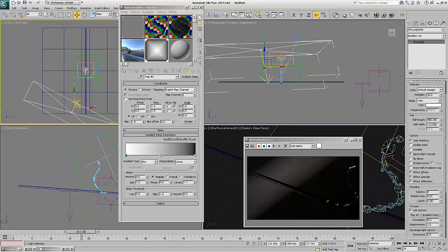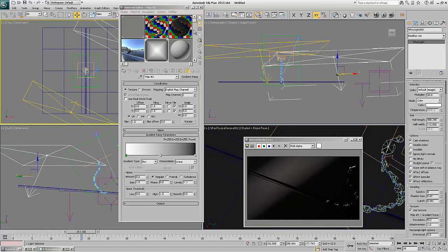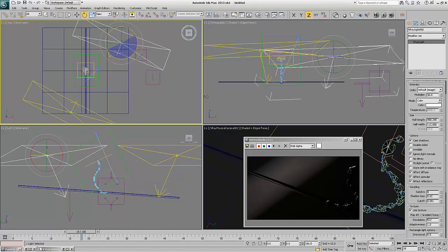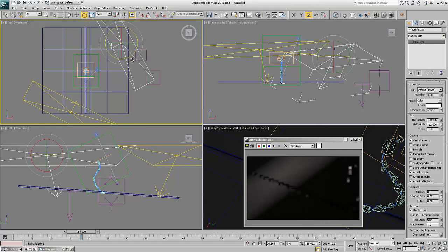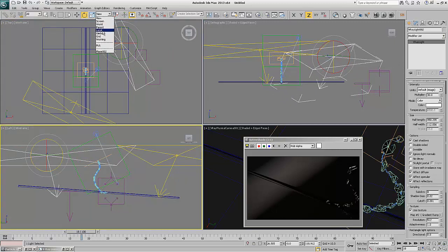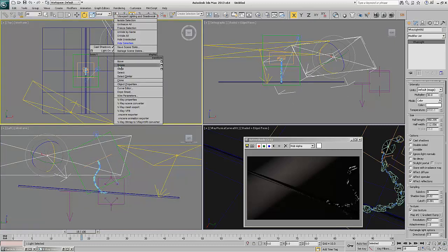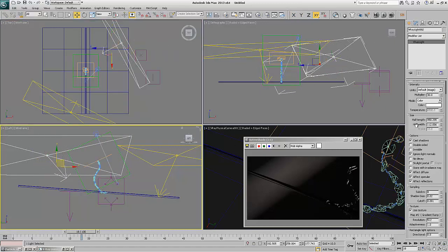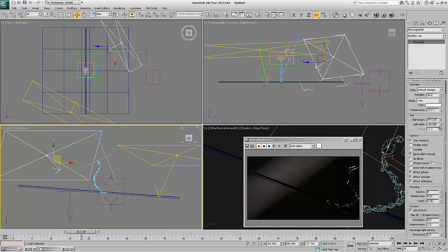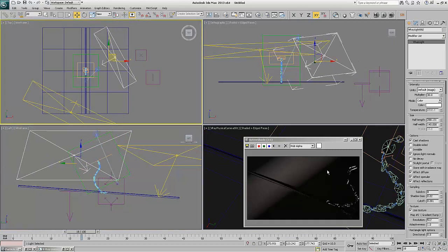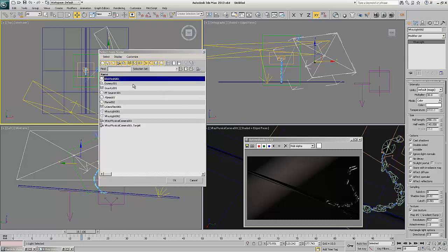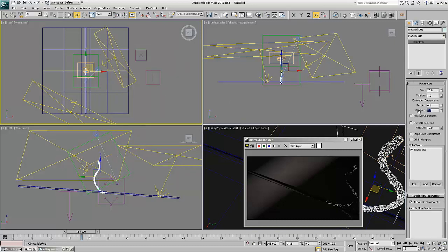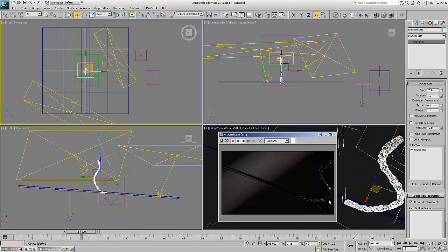Now just for fun, I'm going to take this light and copy it behind, rotate it around, and find hopefully a sweet spot there. And you can see also our particle system is low res. So if we hit that blobby mesh and turn it up in the viewport just a little bit, maybe a 2, about 1, we're getting a little more roundness there, and that kind of helps us see where that light is reflecting.